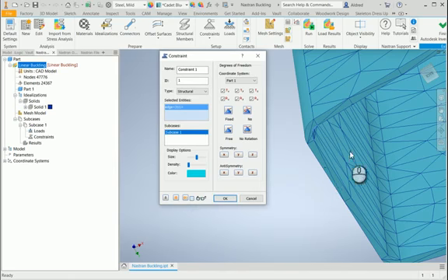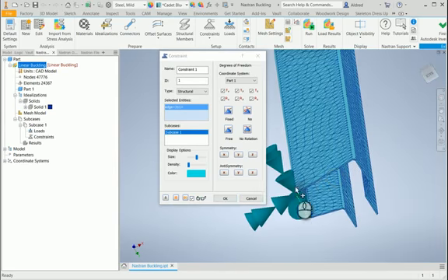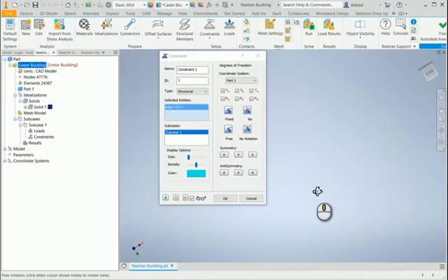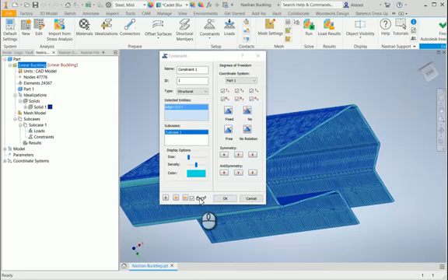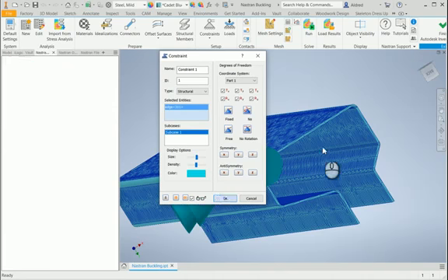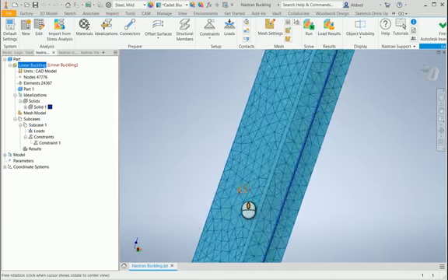To see what the constraint looks like, click on those little glasses over there, and you'll see that it isn't able to translate in the X, Y, and Z directions. It's not able to rotate in the X, Y, and Z either. Just to take a look at the density, I can put that up, and you'll see it will show a lot more arrows. It's taking a bit of a while, and we seem to be having some graphics problems here. Okay, try again. I'm going to click on OK, and it's showing me where my constraint is.